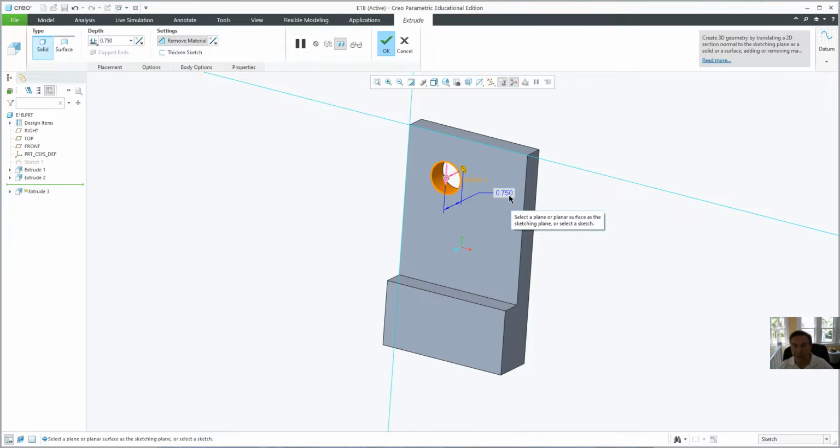Well, let's say all of a sudden instead of 0.5, the manager comes and says, I want that 1 inch thick. 0.5 is too thin. Make it 1 inch thick. You make this area here 1 inch thick and hit enter, and you don't pay attention that now that hole is only 0.75. It's not a through hole. It gets sent out. They make 1 million copies of it. They get shipped to you, and all of a sudden it's like, oh, it's not drilled through. What happened? You're in trouble. So design intent helps you prevent these little accidents from happening.